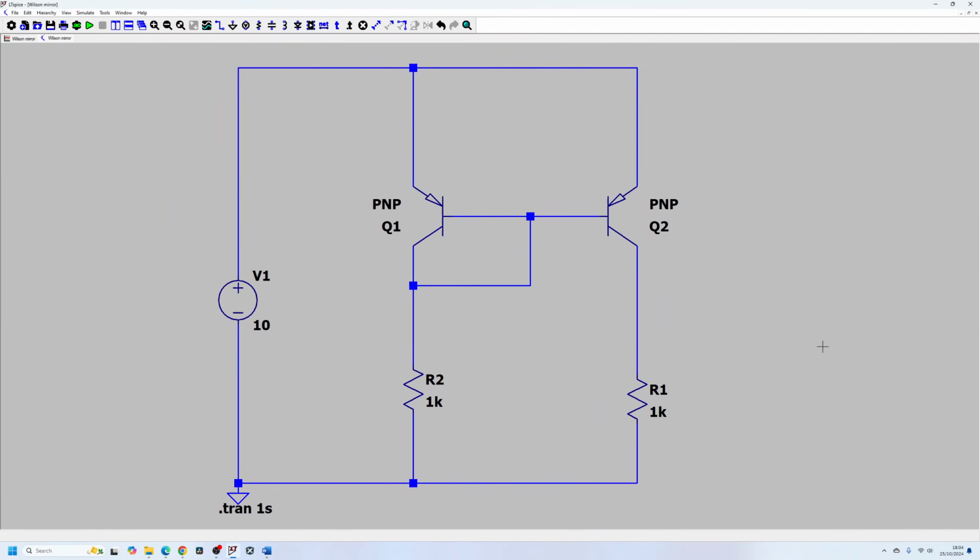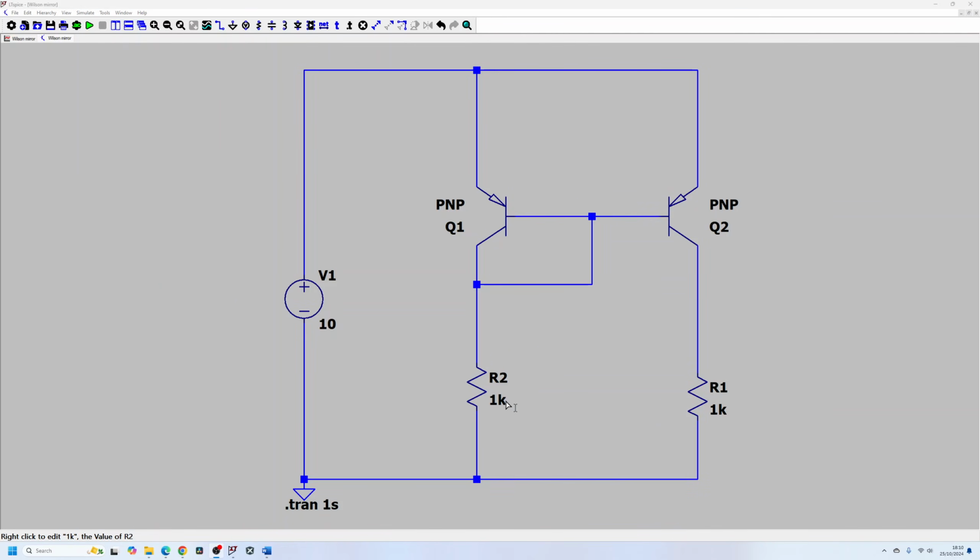So firstly, the basic current mirror. You can see that we have a 1K resistor over here. We're going to have roughly 9.4 volts over here. So I'm just going to move this up to 10.6, just so that we have a nice, readable current flowing in this direction.